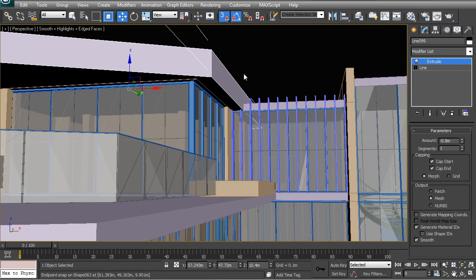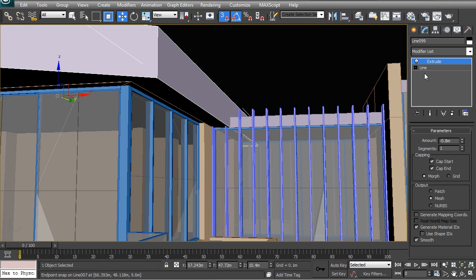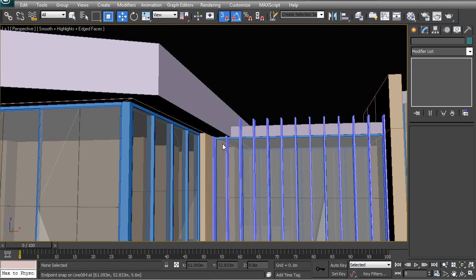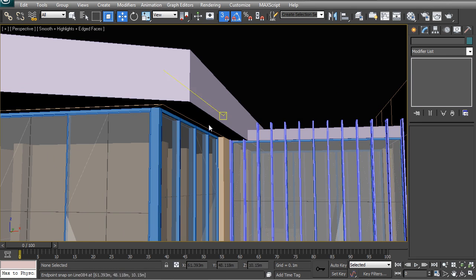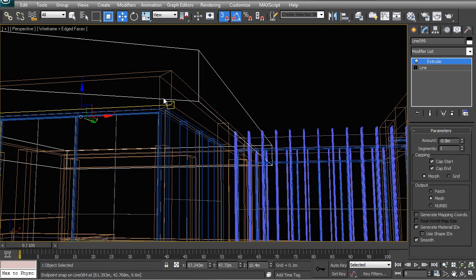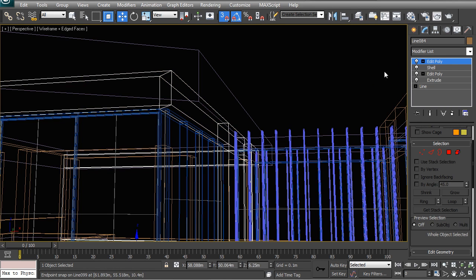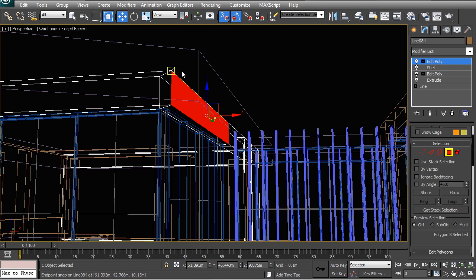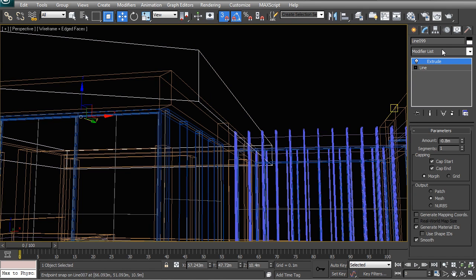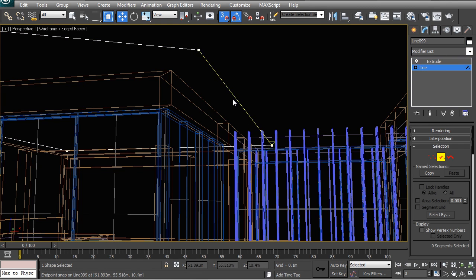This is a little bit of a design junction that we need to solve, is we have the roof interfering with these screen elements. So either you can go and cut the screen elements lower, which means that you won't really have a very pure architecture. Or what we could rather do is move this edge inwards slightly so that it lines up with this original wall underneath. So let's go ahead and do that. I'm going to select one of these polys and just read off the X coordinate. I'm going to copy that, Control C. And then I'm going to come in here and take this edge and just move it into that same plane.